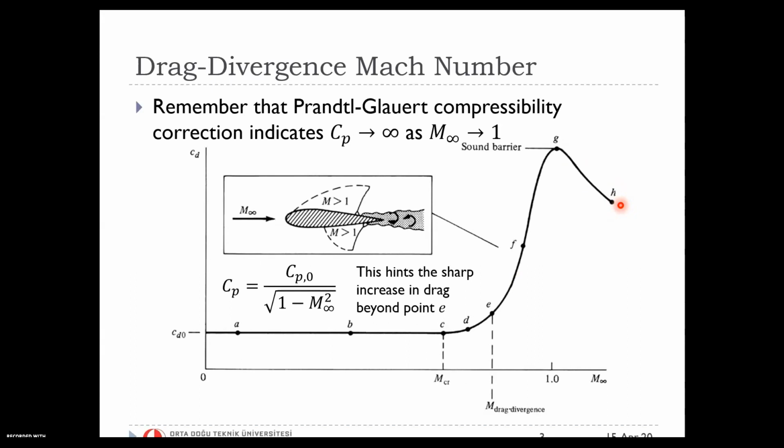Okay, that's actually one way, and the other way is to decrease this peak value of drag coefficient, which will allow you to overcome the sound barrier with relatively less power requirements. For the first case, in order to delay this critical Mach number, you can actually use a thinner airfoil, right? Because I showed you earlier, thinner airfoils, because they generate less perturbation in the flow, would have a larger critical Mach number, and as a result, the drag divergence Mach number for a thin airfoil will also be higher.